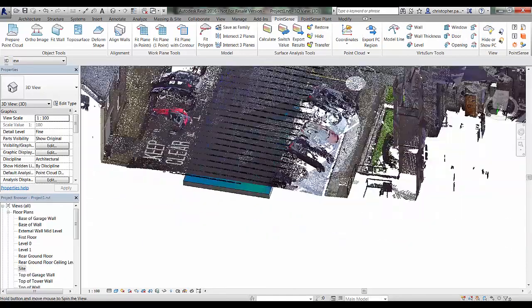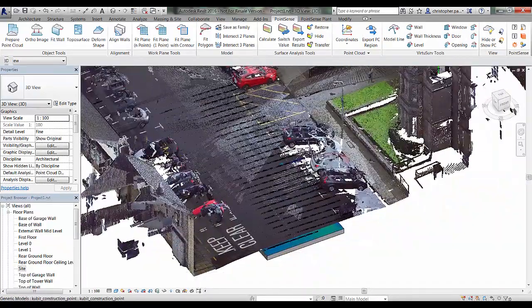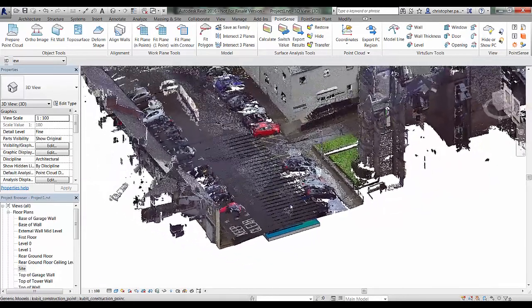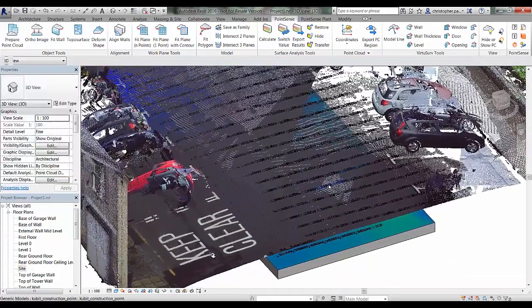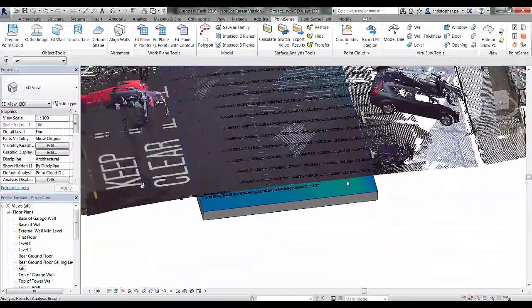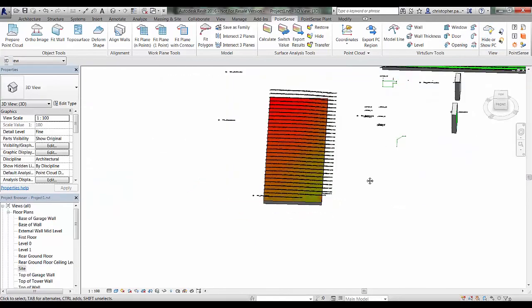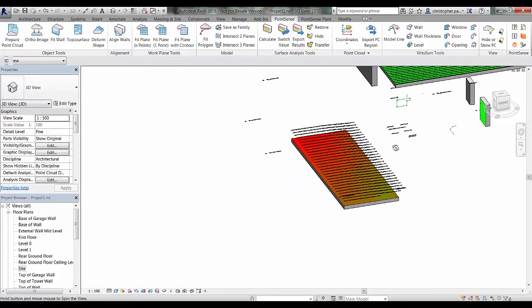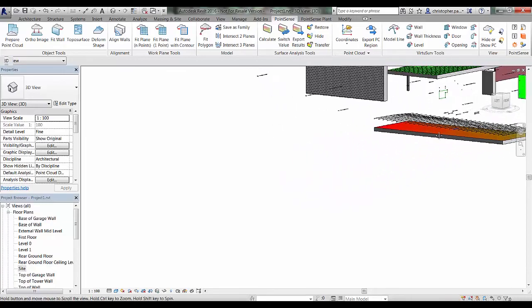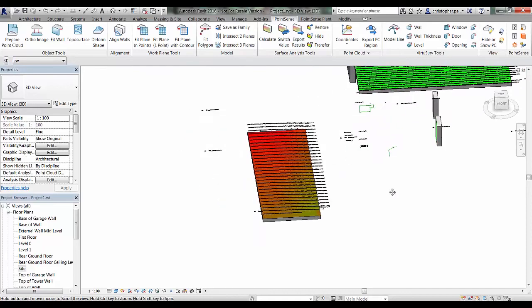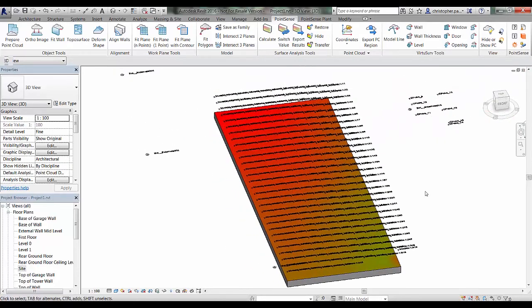You can see we now have 330 construction points, and if I navigate around slightly you can see that these are generally increasing up that slope. So in one of the later tutorials we're going to use those to create a topo surface. If you go underneath you can see there's a generally increasing gradient up that road. So that's construction points.